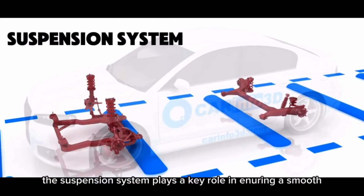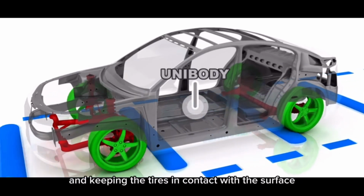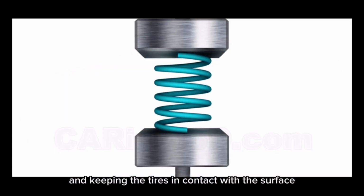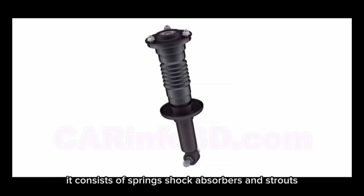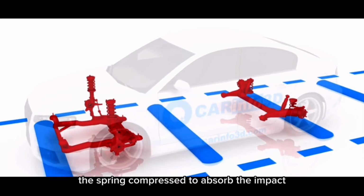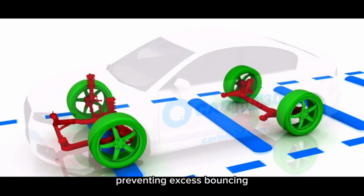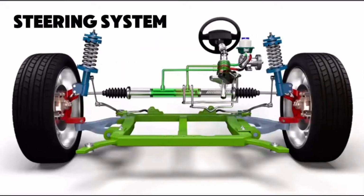The suspension system plays a key role in ensuring a smooth and stable ride by absorbing road shocks and keeping the tires in contact with the surface. It consists of springs, shock absorbers, and struts. When the car encounters a bump, the springs compress to absorb the impact, while the shock absorbers dampen the rebound, preventing excess bouncing. The steering system.